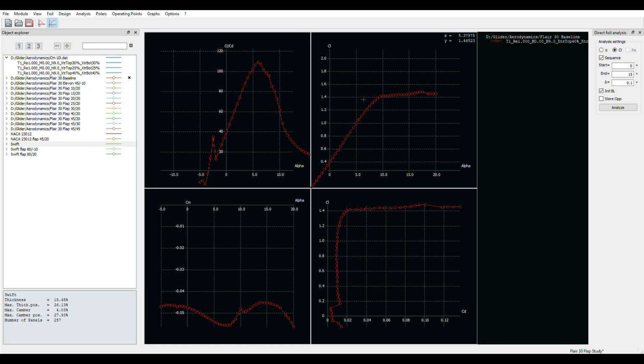Once I had these data points in there, I was intensely curious as to what happens when you put the flap down. I felt that a normal flap setting for takeoff or initial landing approach would be about 20 degrees, anywhere from 15 to 20 degrees. I use about 20 degrees on my wing. Lots of aircraft use only 10 or 15 for takeoff. It varies, depending on the airfoil and the aircraft.